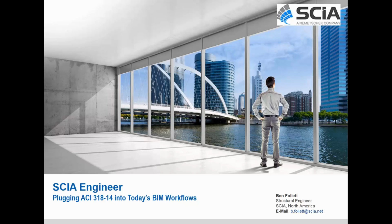Well, we have actually modeled such a thing in the Athens Opera House. We have a ferrocement canopy on top of it, which is 330 feet by 330 feet, and it's fully supported by springs and dampers. So you can do that, but you cannot have the non-linear behavior of it, meaning you can have an equivalent linear damper.